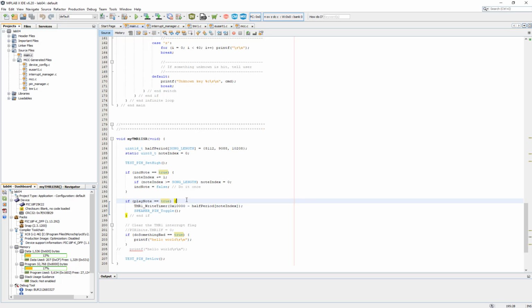You want to tell the interrupt that the next time it gets in, it sees that flag, which means the user has done something to the board. Very important, not just for this one, but also for the lab. Make sense? It has to be true in order to play it because someone pressed it. The interrupt is being called very frequently, only 4.1 milliseconds. All right?